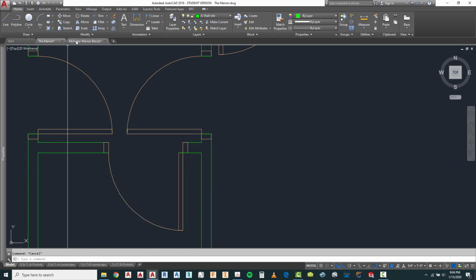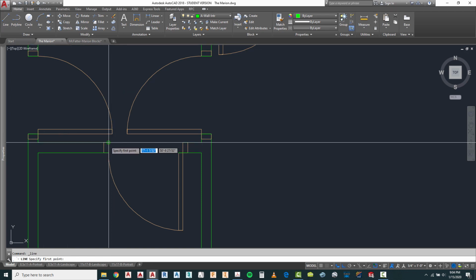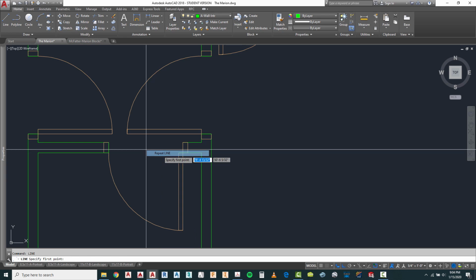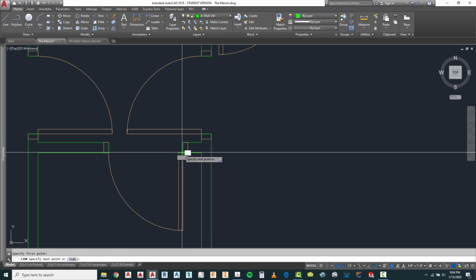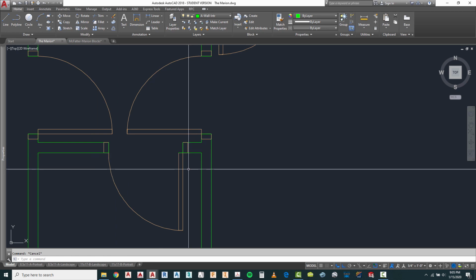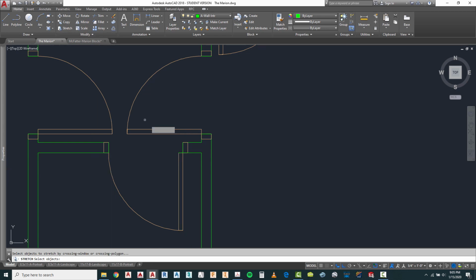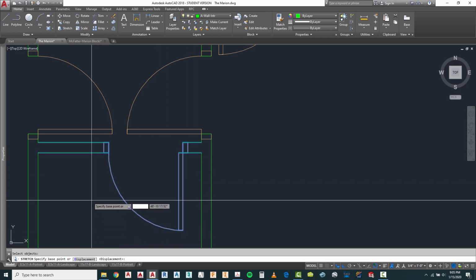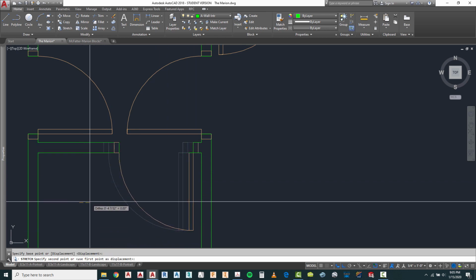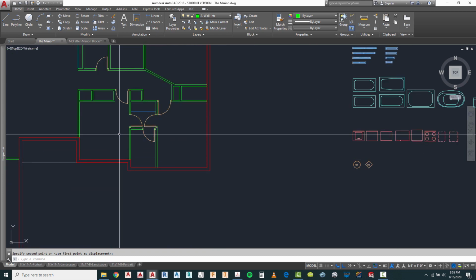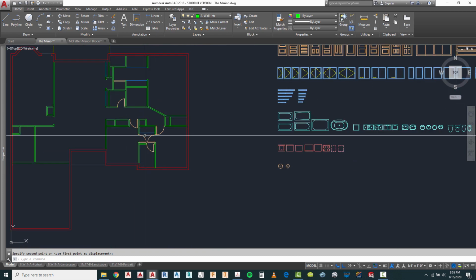This out of the way here, and I will complete that door by drawing the lines here and repeating the line work and drawing it here. And then I'm going to stretch this and bring it closer to the wall in there. I'll use the stretch command with a crossing selection and move it over in here. And there I have those doors going into this bathroom.